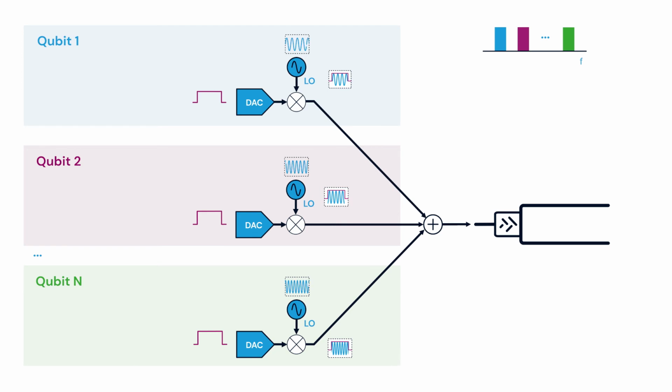So we can have one cable for multiple qubits, since each of the qubits is addressed on a single separate distinct frequency. What is important to realize is that for each of the qubits, we need to keep a separate oscillator that keeps track of the phase of the single qubits. We cannot, in any way, stop these oscillators, because we may risk abruptly changing the axis of rotation of a specific qubit. Therefore, it is important to have n different oscillators for n qubits.